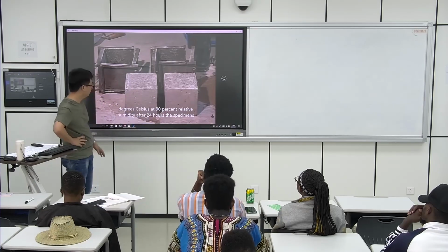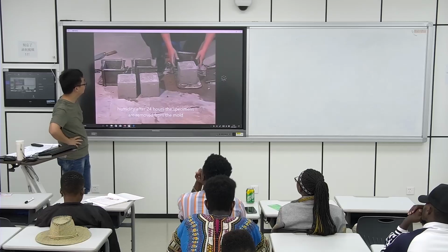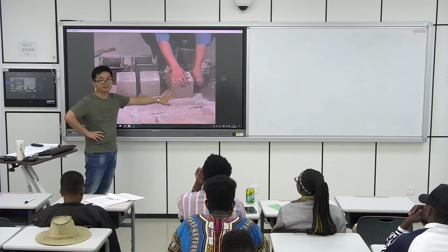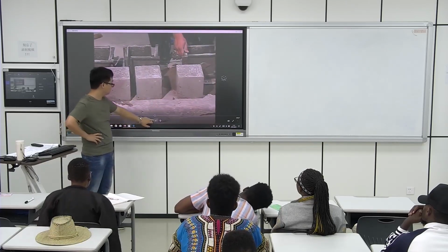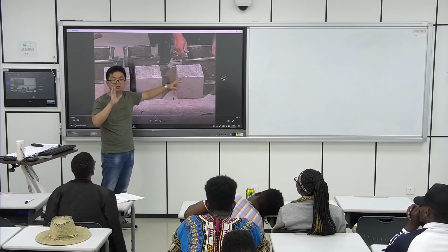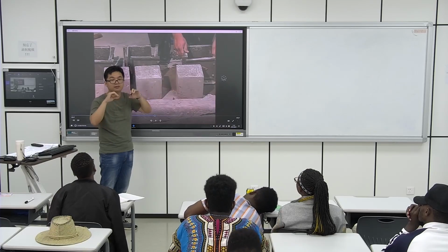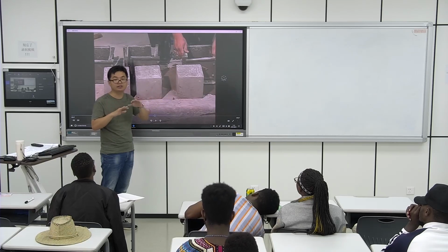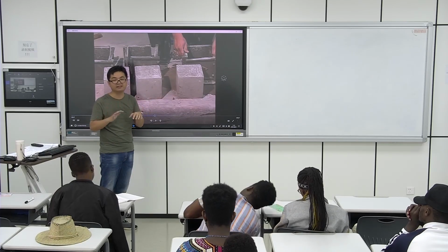After 24 hours, the specimens are removed from the mold. Remove the mold and get the standard specimens. Look here, we see it is smooth, right? But in the micro view, we know the micro cracks already exist between the cement paste and the aggregate.